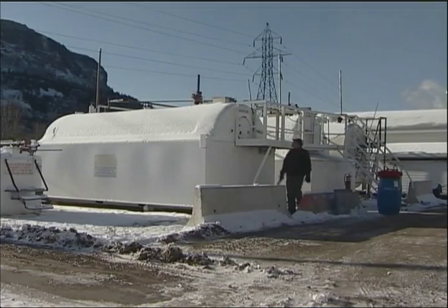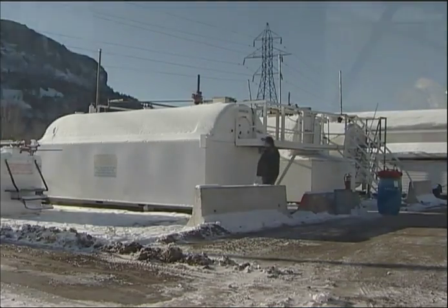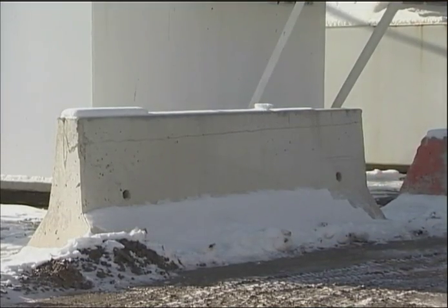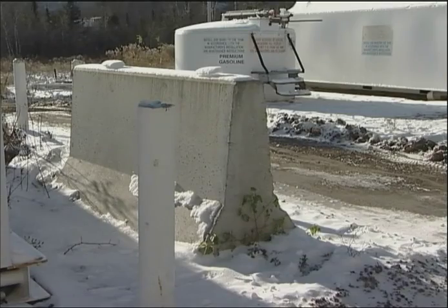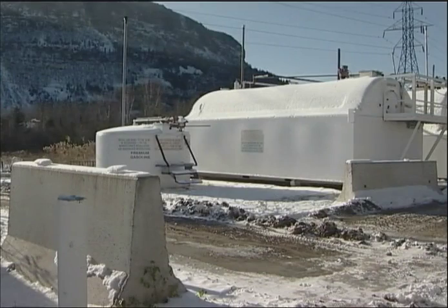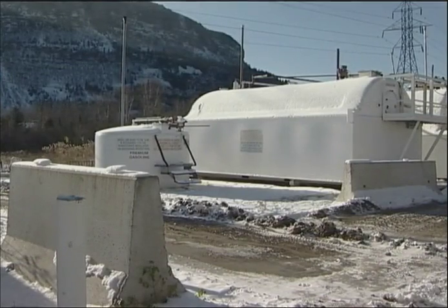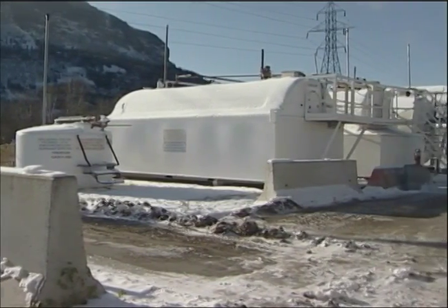Crash barricades must be installed to prevent vehicular traffic from entering fuel site. Crash barricades can be constructed out of concrete, steel pipe, or large boulders, but not be constructed out of wood.